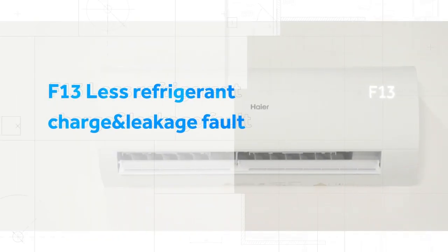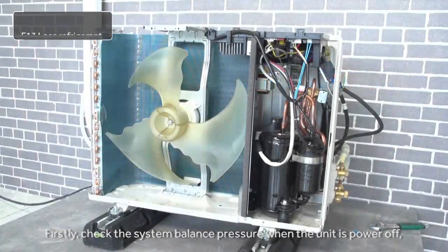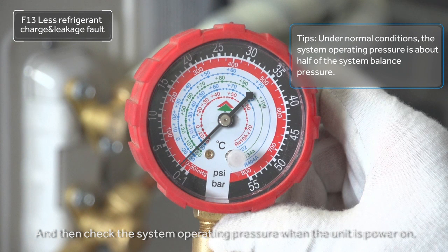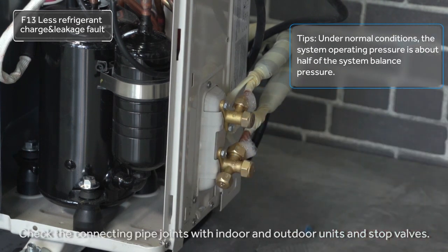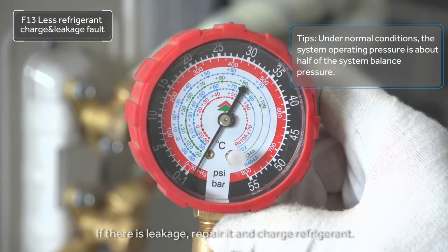F13 Less refrigerant charge and leakage fault. If the indoor unit display shows error code F13, it means less refrigerant charge. Firstly, check the system balance pressure when the unit is powered off, and then check the system operating pressure when the unit is powered on. If the pressure is lower, check the connecting pipe joints with indoor and outdoor units and stop valves. If there is leakage, repair it and charge refrigerant.